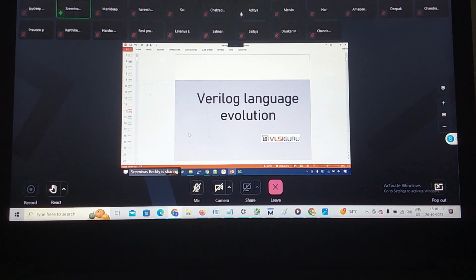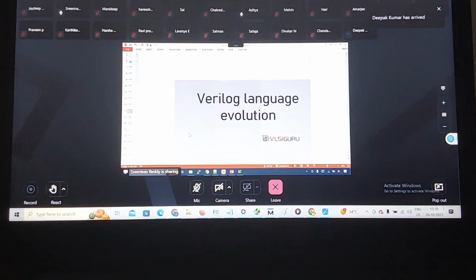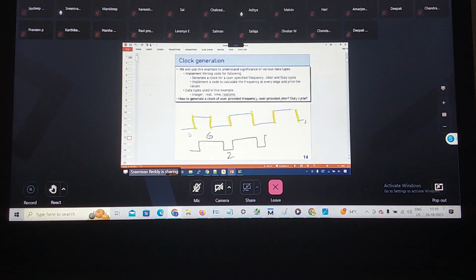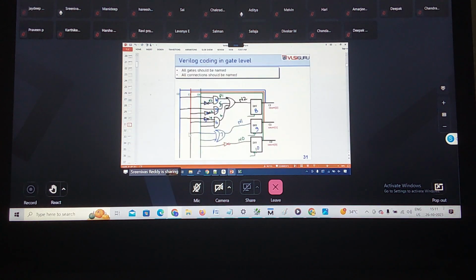Let's say you have come up with some circuit. What is the guarantee that it works? That it is a correct circuit? I'll show you one example. This is an example of a 3-bit up counter. I will tell you that these 3 AND gates, these inverters, this OR gate, XOR gate, NOT gate, and 3 flip-flops put together make a 3-bit up counter. How do I confirm that this actually behaves like a 3-bit up counter?